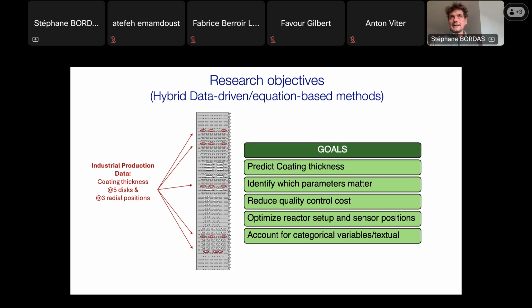We could say between flight 1 and 10,000, the crack will grow by 1 centimeter, and therefore we will need to have an inspection of that aircraft before flight 5,000 because we expect that the crack should not grow more than 2 millimeters, otherwise there will be failure in the aircraft.